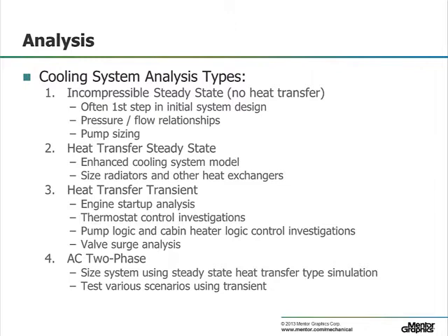Moving into the different types of analyses, there are a number of different options the engineer has. Oftentimes, the cooling system designer will start building a model by doing a series of steady-state analyses without the use of the heat transfer solver. The goal is to characterize the pressure drop of the cooling passageways and size of the pump. They would use fluid properties close to the expected operating condition of the system.